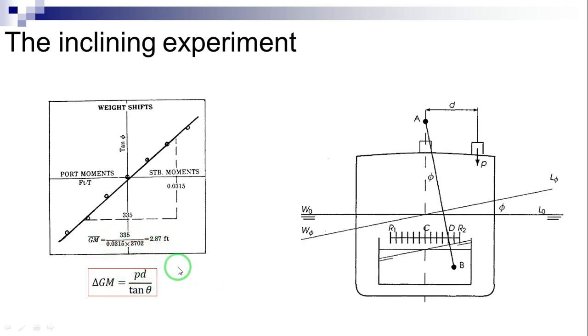Static stability of floating wind turbines. The restoring in case of floating wind turbines is achieved through 3 mechanisms: water plane area, ballast, and the mooring system, which are described further in the following sections. Restoring from water plane area. Restoring from a structure's water plane area is provided by the moment that the structure's water plane area makes about the structure's center of rotation.